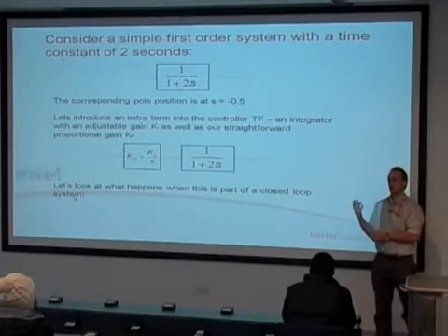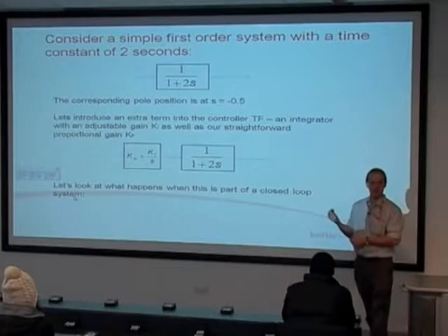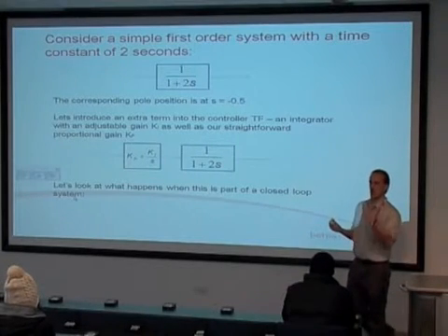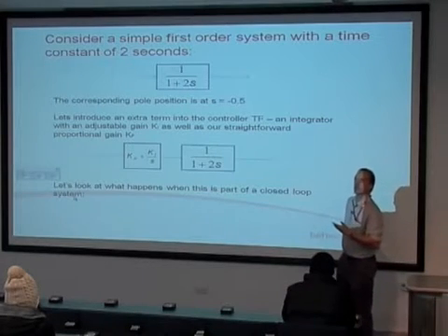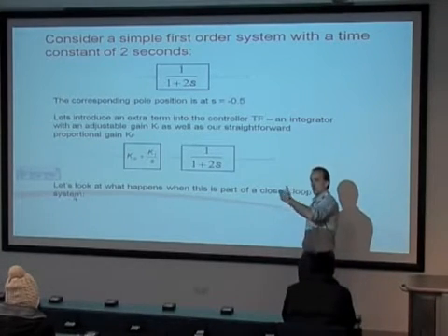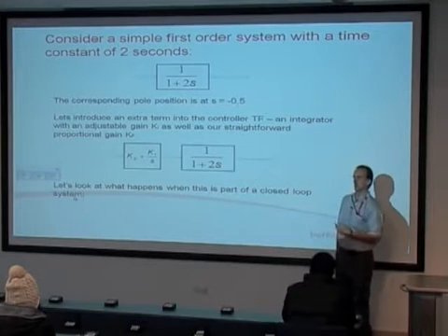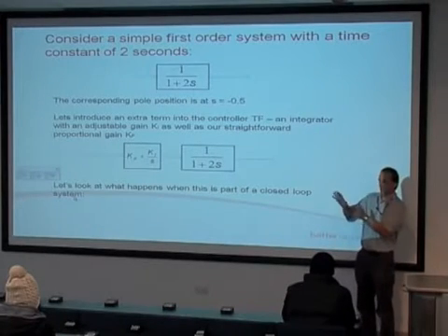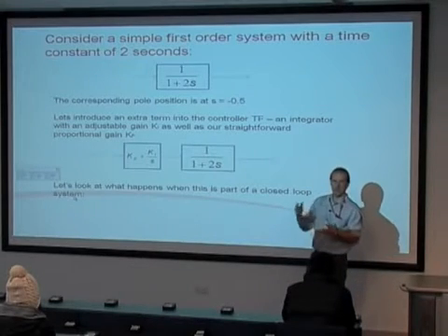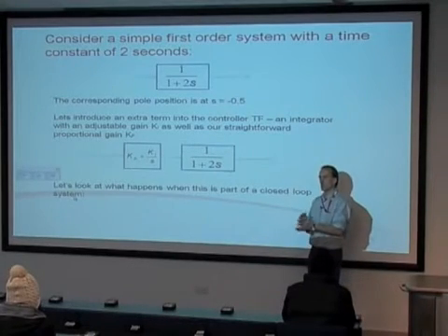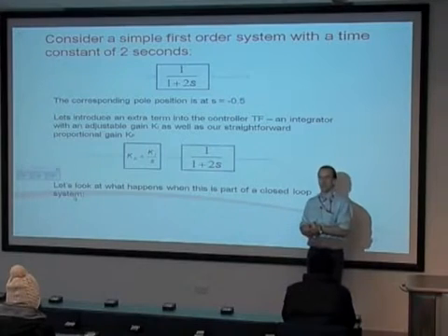Typically, a cruise control is designed to control speed. So the input variable is a desired speed: I would like to go at a steady 70 miles an hour. Then the process, the forward path boxes, are to do with the engine and the transmission and the wind resistance and all the things that govern the dynamics of the car.